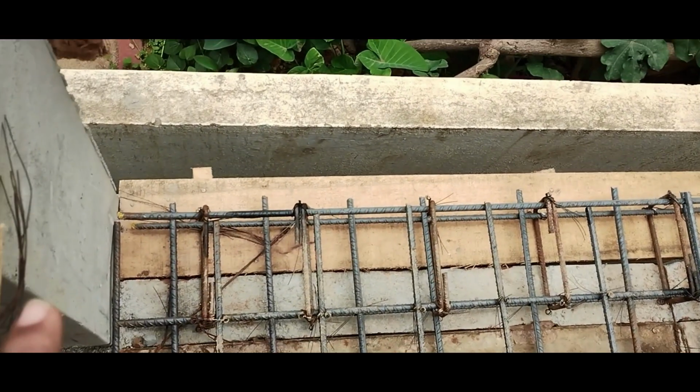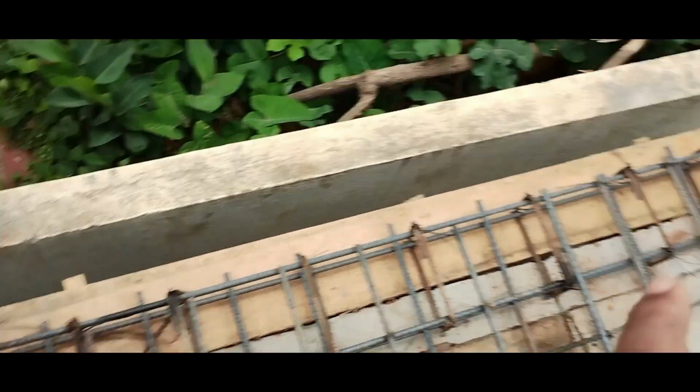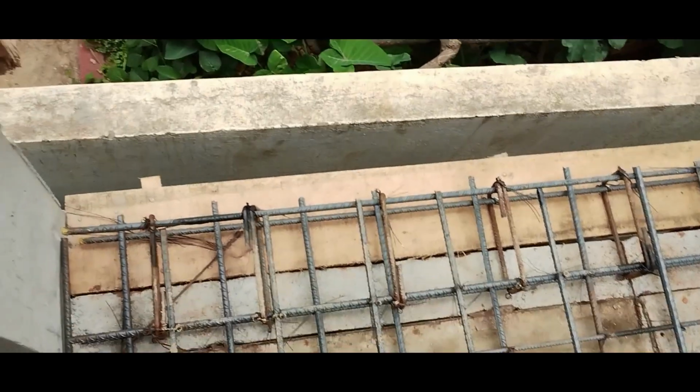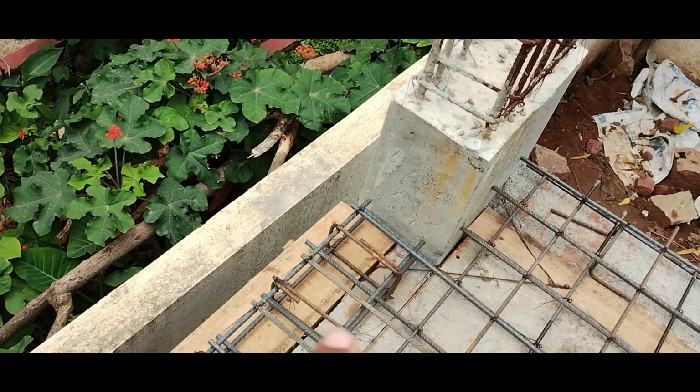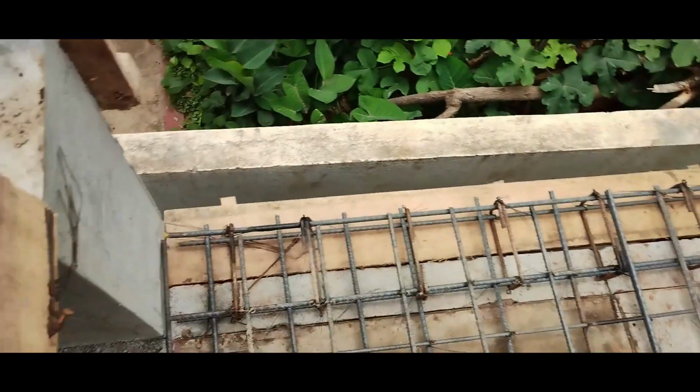This practice is also done on the side, where they give the section from here to this point to that point. Beneath this we have a support from the wall also. That's why we have done this. If there is no wall support, then what you can do is cast the column until this point, take the reinforcement into the column part also, and then cast the rest. You can do that practice also, no problem in that.